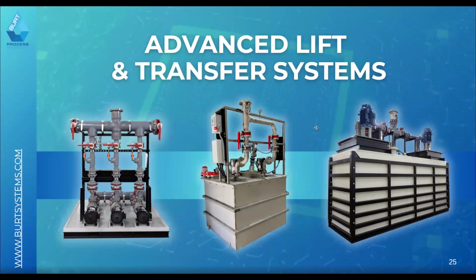Yeah, I mean, 99% of lift stations are duplex. Some are even triplex. And the other thing you can also do, which we didn't mention in the poll question and which you don't see too much, is combined flows. So you can say, I want to run both pumps in series to get a higher level of flow. You see that a lot where you have a system that requires a very specialty pump design.